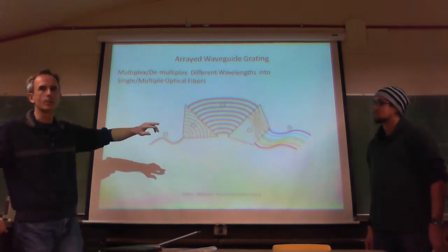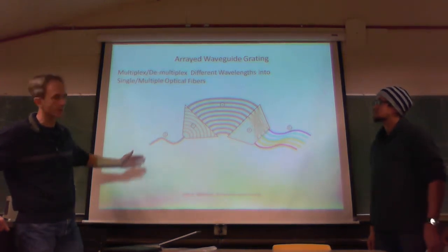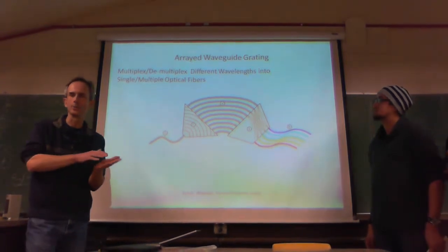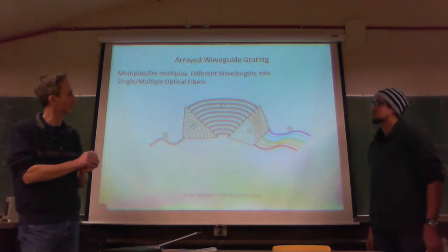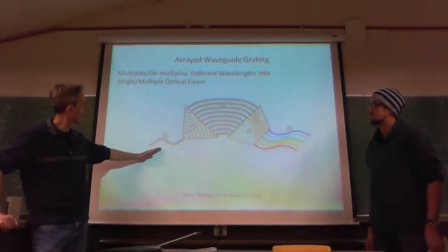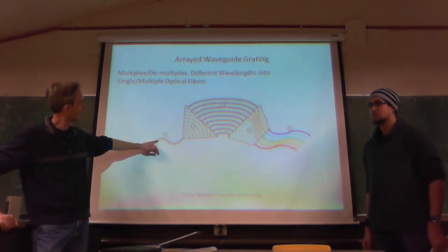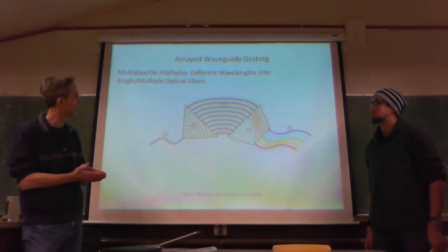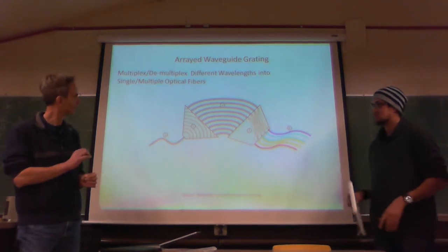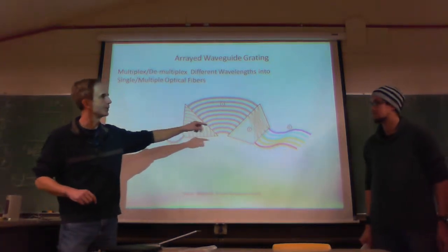So what the patent device that we're looking at here aims to do is, on this end of the device, be inserted in. It's basically meant for a fiber system. Steve will go into in a few minutes what the device actually looks like, but it's basically putting this grating in close proximity to this fiber, such that the evanescent field of the mode traveling in the fiber can interact with that Surface Acoustic Wave device. Depending on how you tune the device and what the pitch is, you can selectively filter out any of these frequencies that are traveling in the fiber.